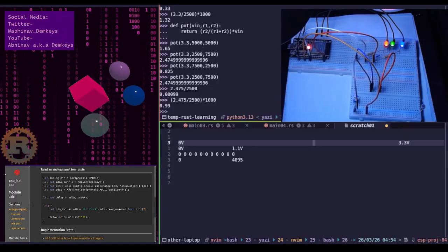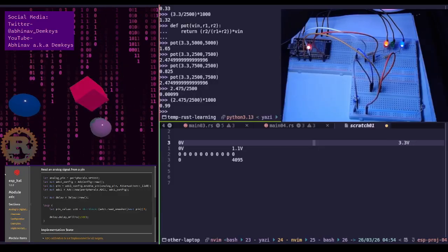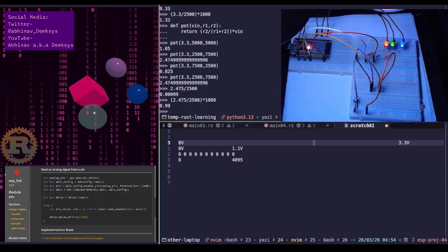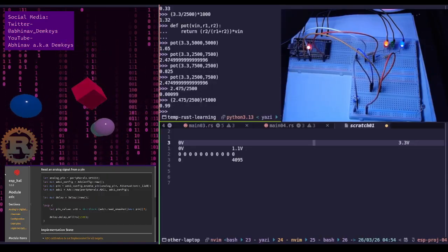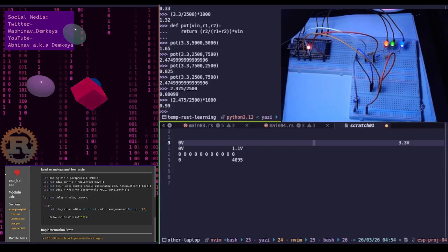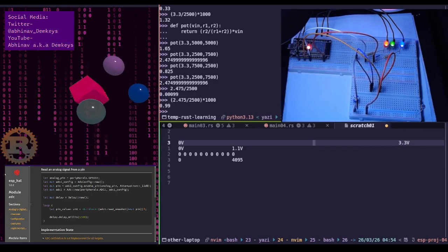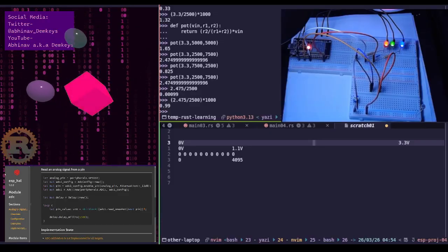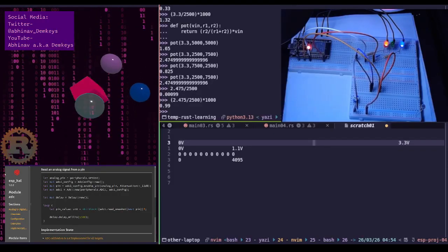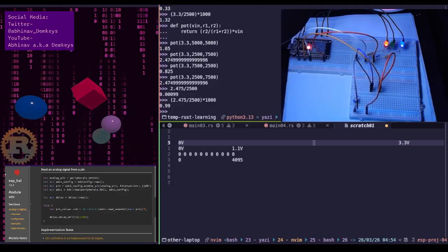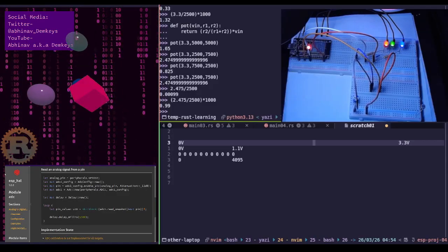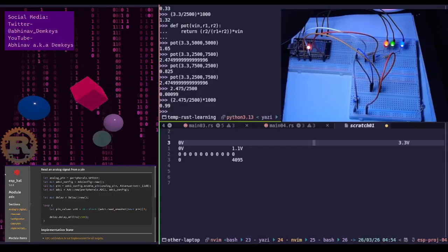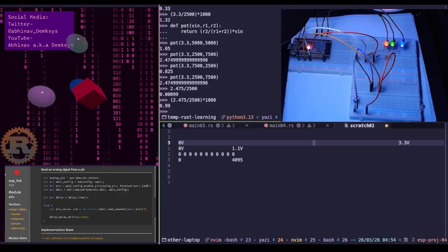Where your calculation does matter: source impedance. While you don't need to worry about damaging the pin with current, your calculation relates to something called source impedance. The ESP32 ADC works by charging a tiny internal capacitor, sample and hold. If the resistance of your potentiometer is too high, for example using a 1 mega ohm pot instead of a 10K pot, the trickle of